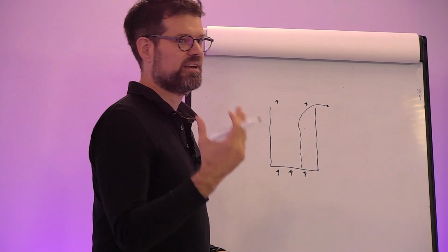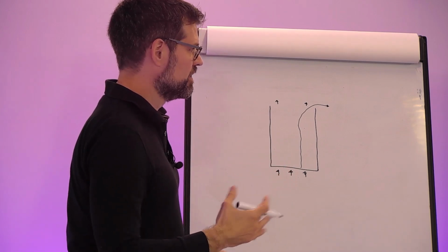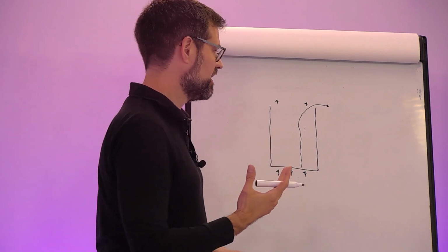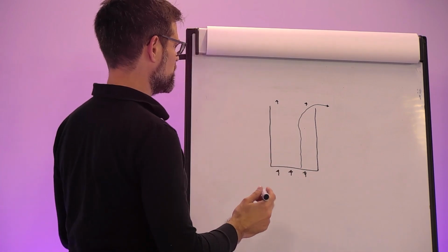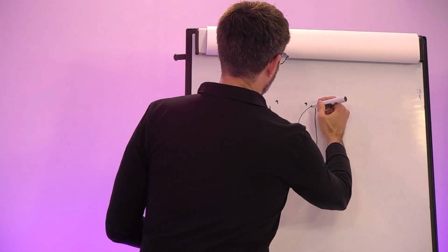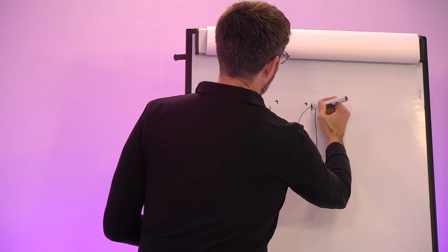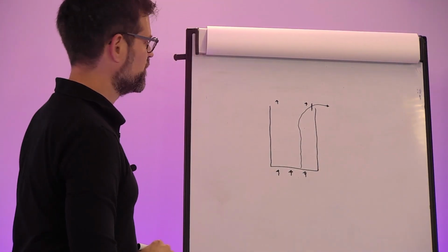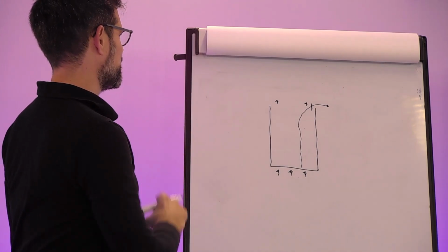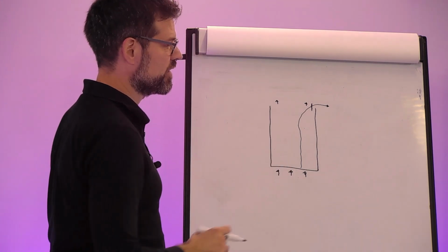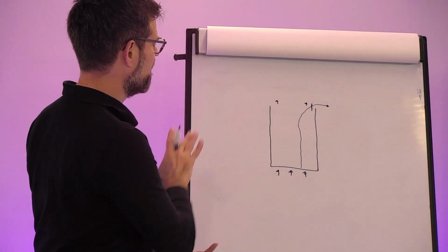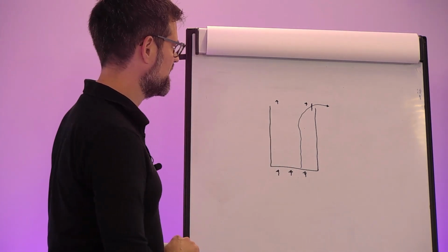We already knew from conventional wastewater treatment that floating scum can be a problem, and there's a really easy solution for that. You just place a baffle in front of your effluent weir, and that will prevent floating stuff from flowing out of your reactor. That's step one in improving your effluent suspended solids.